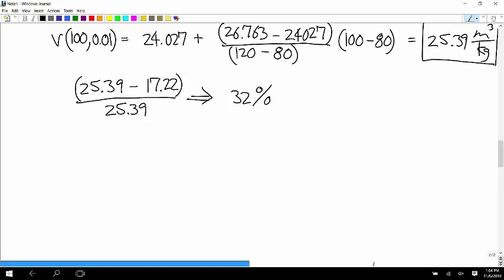Would you expect this approximation to get better if the temperature increased or worse? Better, so the ideal gas approximation is best for low pressures and high temperatures, okay? So if you're at the lowest temperature you can be at, that it can even have the identity of being a vapor at a given pressure, then you're getting pretty bad results. Okay, so part B asks you to do it at a much higher temperature, and I assume that you get a lot closer results for that.